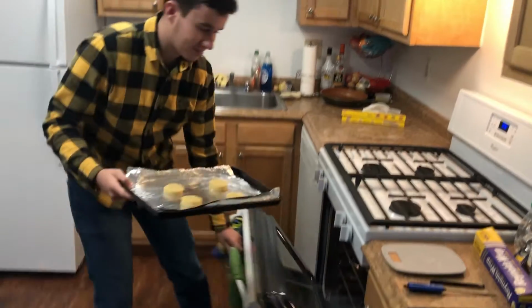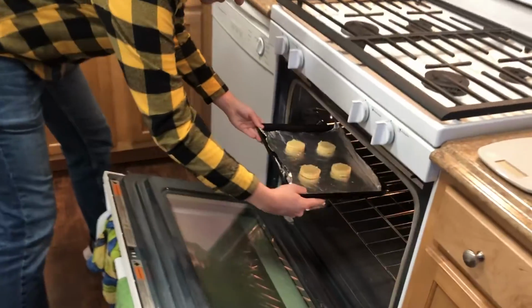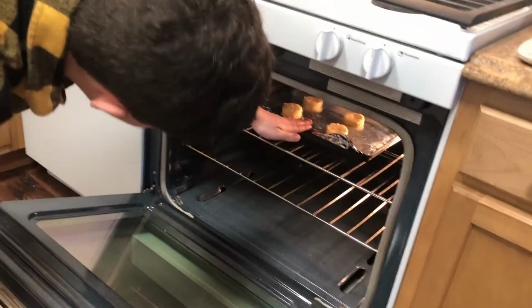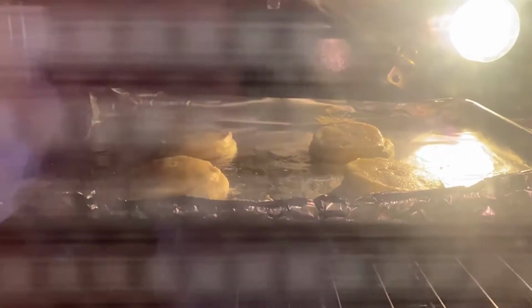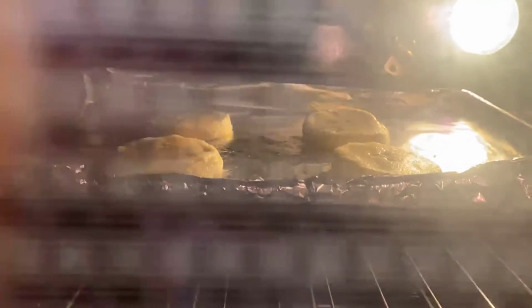Our first cookie baking method is a conventional oven, which is the typical means of baking a cookie. The sugar cookie dough is placed in the oven at 375 degrees Fahrenheit and cooked for 8 minutes. Here we can see two means of heat transfer, radiation from the gas oven and conduction from the pan. Radiation occurs as the combustion of the gas in the oven creates a constant temperature atmosphere for the cookies to bake in. The cookies are completely surrounded by the heat, absorbing it in and causing the raw dough to transform